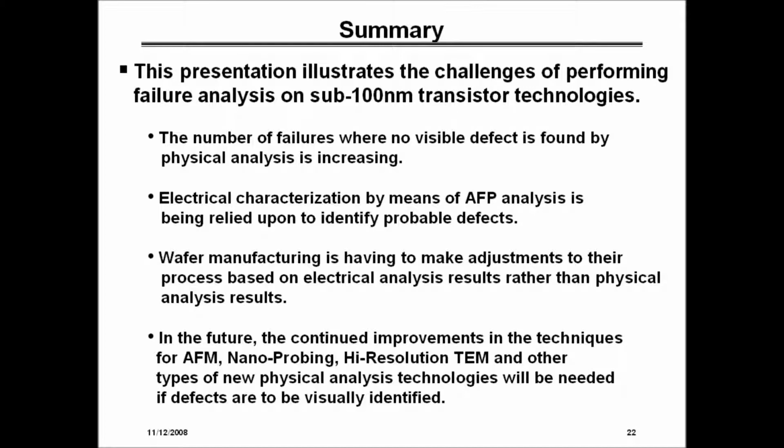Okay. I have another question from Jay. We seem to have plenty of time, but there's a question from Jay about case study number 1, and he'd like to know, how did you determine the short was through the gate versus an external short, such as a silicide short from gate to source or drain?